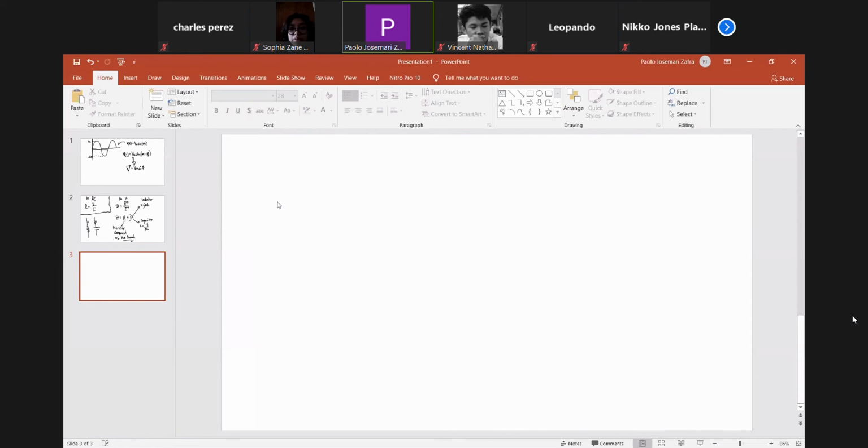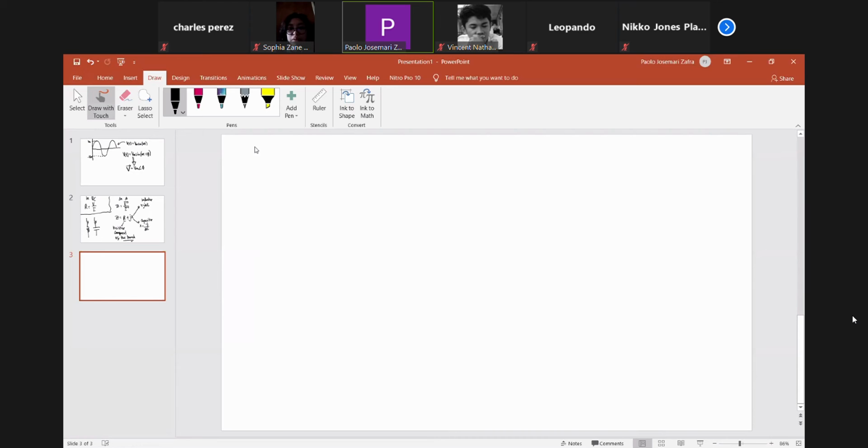Also, in your AC circuits, you will also come across purely inductive, purely capacitive, and purely resistive elements. So that is when the branch, for instance, for a purely resistive element, take for instance X here is equivalent to 0. So we can say that the impedance of this branch is purely resistive. Meaning it draws average power all the time. So that is one of the interpretations to this, if you were to relate this to power analysis later on. So this is what we will be examining for this experiment.